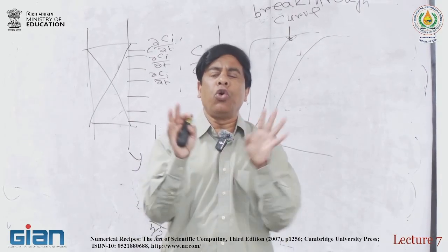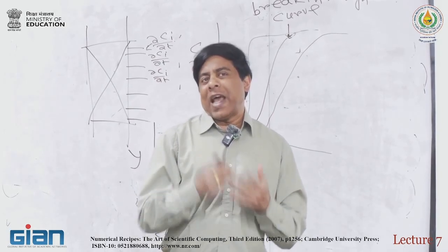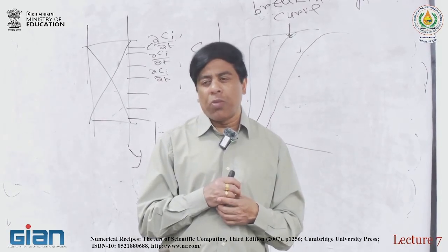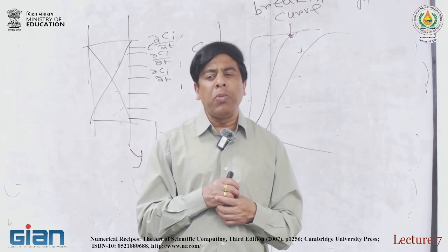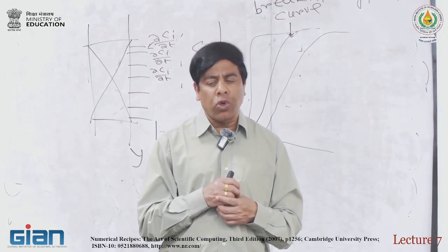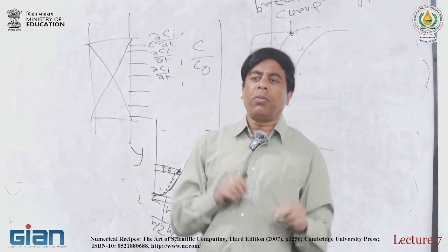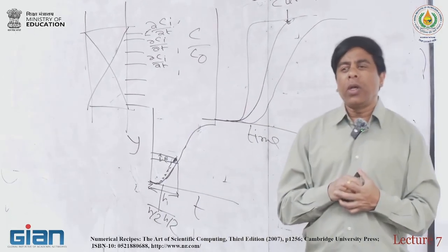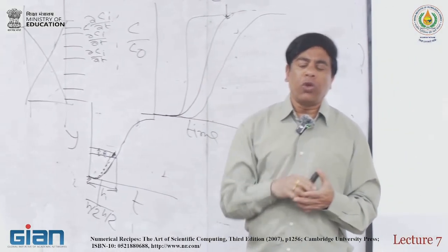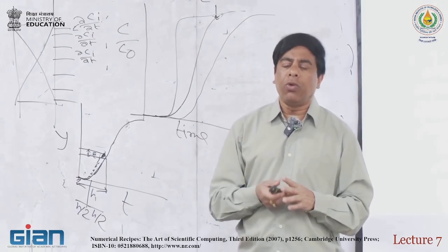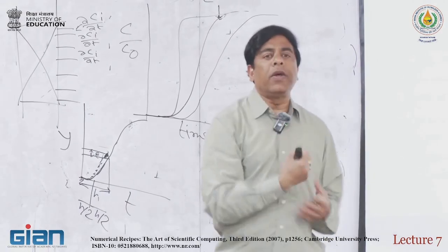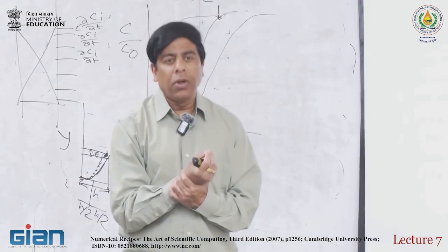There is no sanctity about how much a tolerance should be, but below 1e minus 3, like normalized values, is not recommended. 1e minus 5 is actually very standard, but you can definitely go higher.